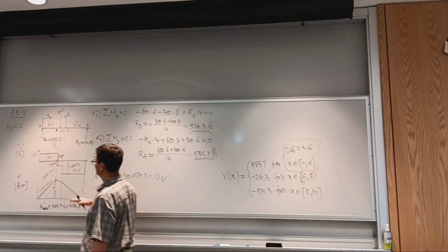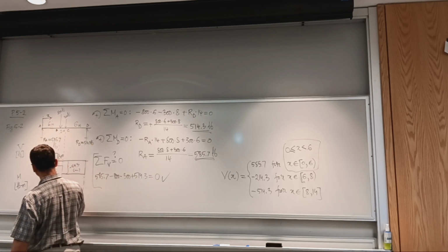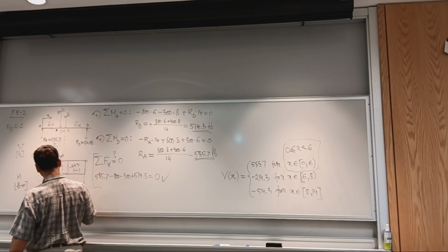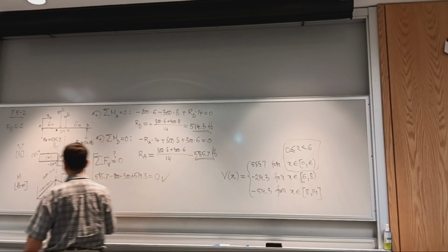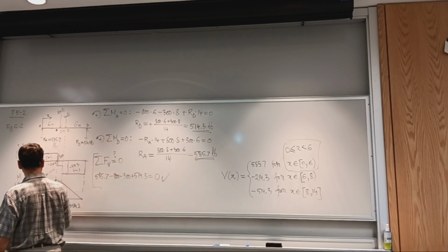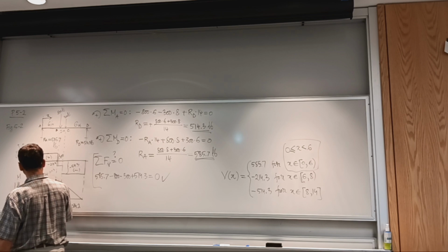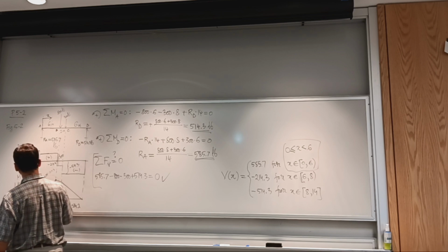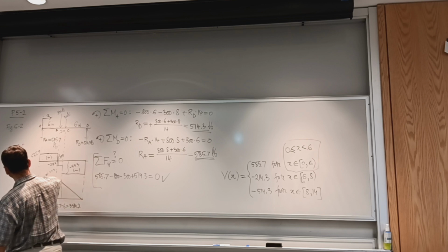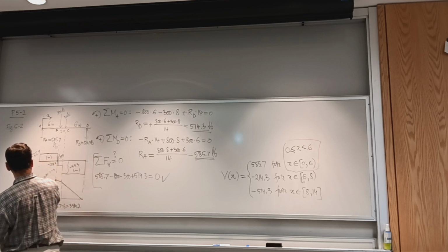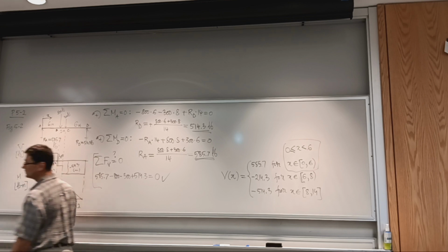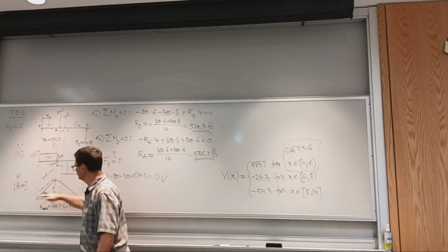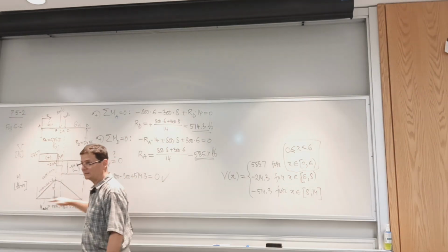If I write the equation of the moment line, it will be piecewise continuous. We can try to write that. If you take the derivative with respect to x, which is in inches, you lose the inches, and it gets you pounds. So the slope is in pounds, because the x-axis was in units of length, inch.